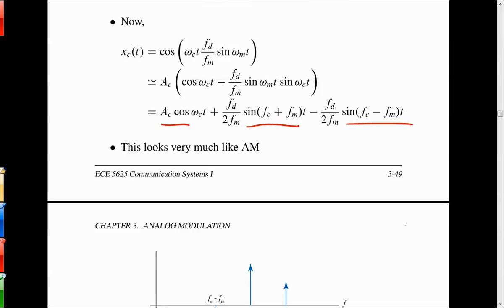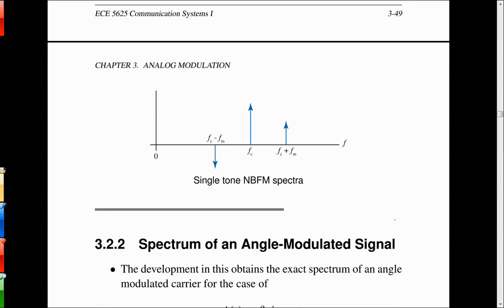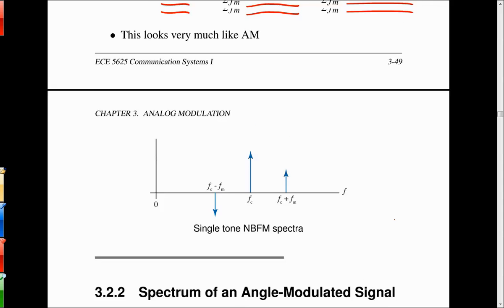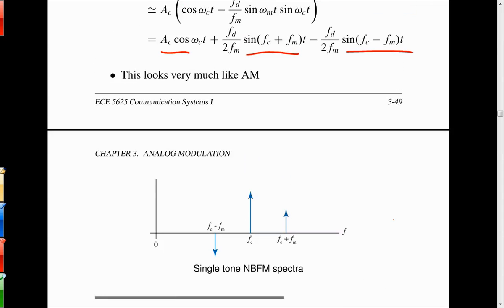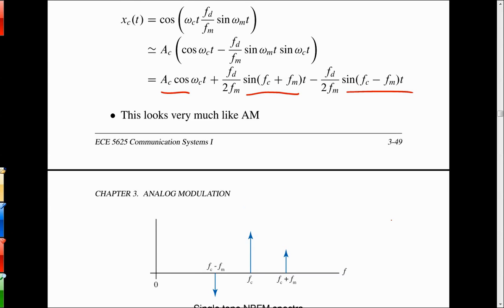So I just drew a picture of the spectrum, and I pointed the sidebands up and down as if to say that they're shifted in phase, actually, because they're on sine carriers, and one has a positive angle and the other has a negative angle. It just comes about from the trig identity for sine times sine, which has that plus and minus.